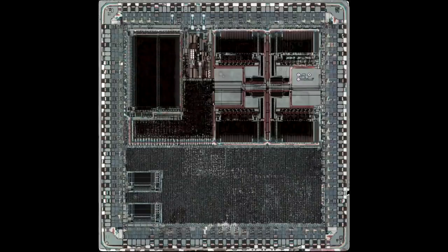After a third dip in the Wink, more metal has been removed. At this point, the delayering is becoming more and more uneven. We can see the ROM blocks have been half etched to a lower layer, while half of the upper layer is still remaining. The wet etching process can be quite difficult to perform completely consistently without adding additional steps such as polishing. And at the time I did this project, I didn't have the polisher available, so I was relying only on the wet etch.